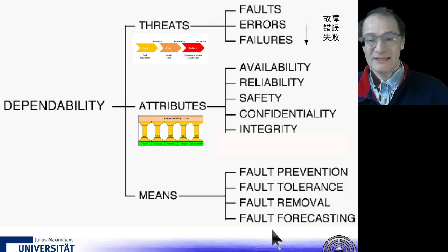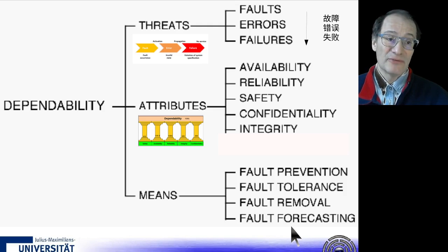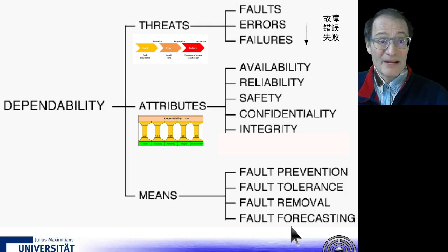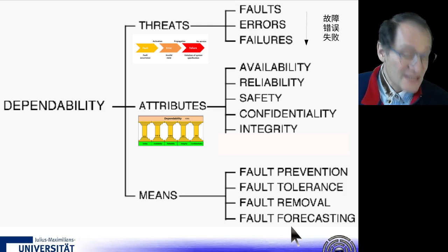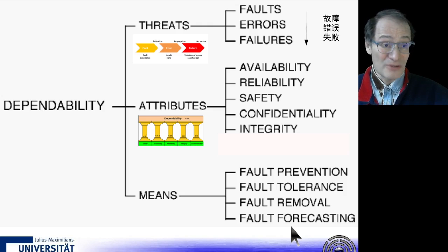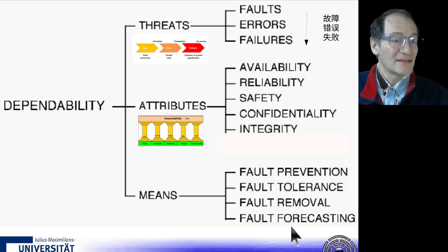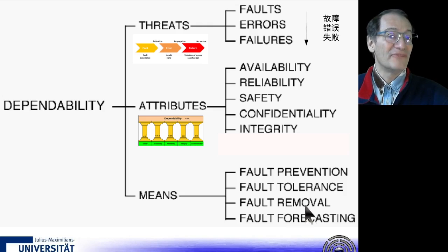And something very important is maybe we don't need to wait until the fault occurs. We have some means for fault forecasting, so we can predict. There is a lot of statistic values when things are going to fail, and we are monitoring the behavior of the machine. And if we find, for example, some vibrations which shall not be there, we can take a look to the statistics and see after these vibrations, these components will fail. Or we know this component is producing this vibration, so we don't need to wait until this failure occurs. So before the failure occurs, we know it will come. Using all the statistic measurements, then we can remove the part which will fail next.